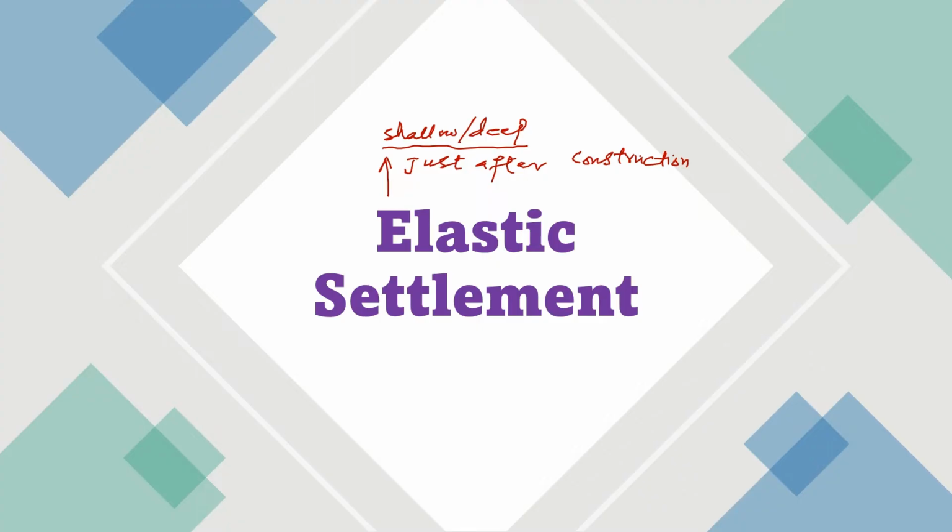There is a clear difference between elastic and consolidation settlement. Consolidation is due to removal of water and it does not start at the initial stage. It takes time to start, but elastic settlement starts just after the construction of the first phase. Whenever you are laying down your foundation, it will start, and it may take 1 day, 3 days, 7 days, or ultimately 1 year to complete. But this settlement remains at the site for a shorter duration as compared to consolidation settlement.